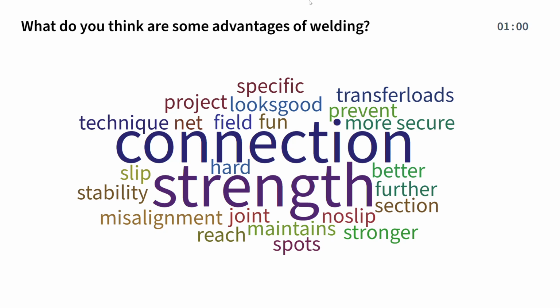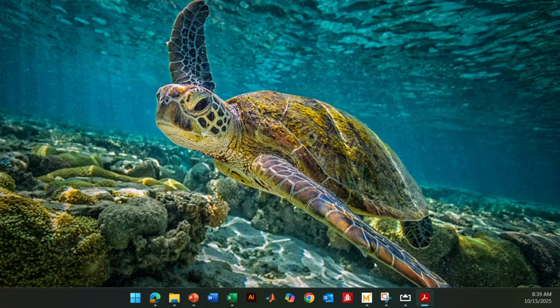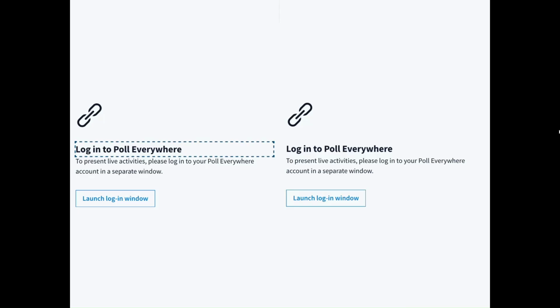If you drill holes in the tension member, you drill holes in the connection, you put everything together, and if your bolt holes don't line up well, like this, it's precise, right? You've got 2 millimeters or maybe a 1/16 of an inch in all your holes to try and align everything, and so it may actually be difficult to deal with alignment issues when you're bolting things than it would be to deal with misalignment if you're welding things together.